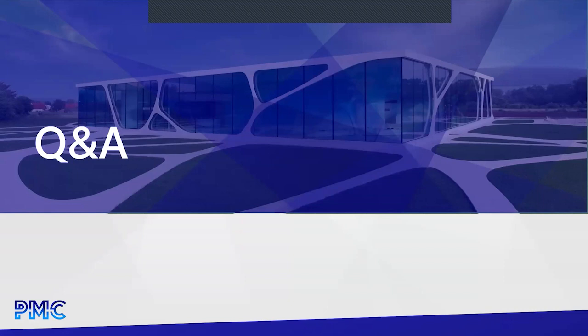And this is very important. You do not want to arbitrarily be trying to move a point cloud around in Revit. This causes a lot of problems. You always want to bring it in origin to origin and pin it right there and never move it. If you're moving it, it's just going to cause problems over the life of the project. So the geolocation is just making sure that our point cloud data lines up with any existing CAD data you might have so that it works together.